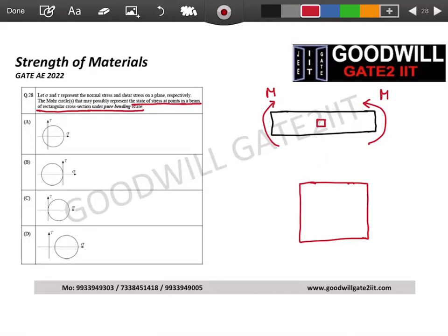And in bending, the stresses are the normal stresses which act perpendicular to the cross section, sigma x. There will be no stresses in the y direction because no one is doing anything in the y direction, right? And there will be no shear stress because there is no shear force. So the only stress generated in bending is in the x direction. Now you should not worry, but ideally this formula of normal stress is basically M divided by I into y.